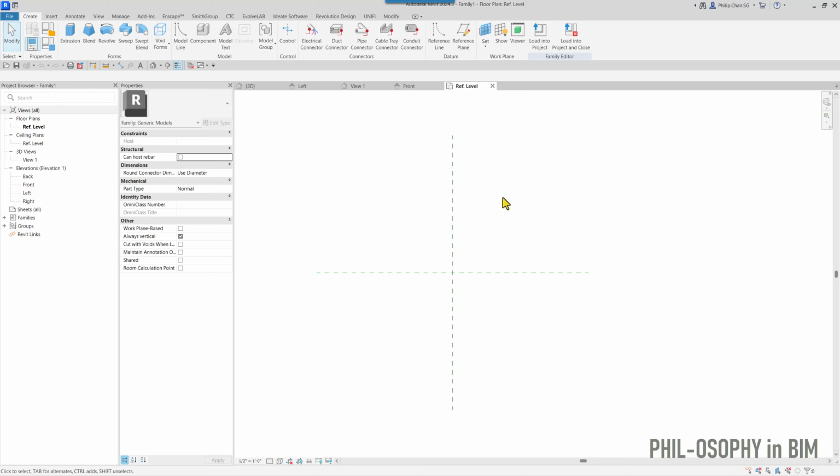For the most part, if you're setting up a framework for your geometry dimensions like X, Y, and Z, you often go with the reference plane. But when it comes to controlling an angle, in this case creating a rotation parameter to control the door swing, you are best using a reference line. Again, I'm in the generic template, and I'm going to go with the reference line here.